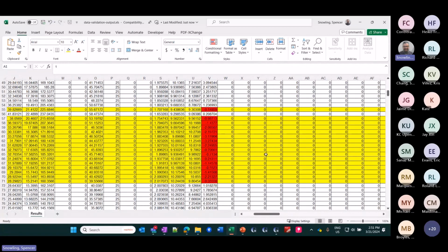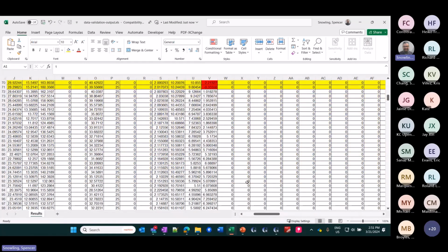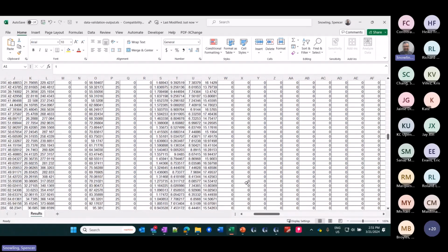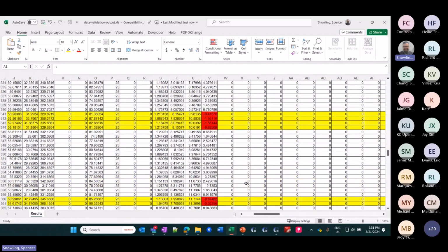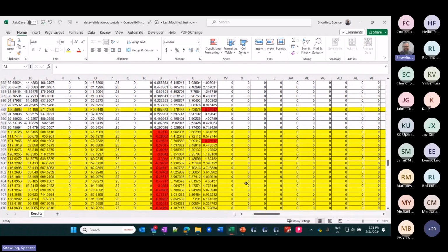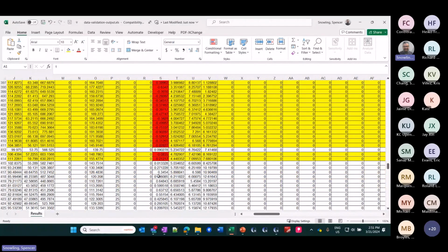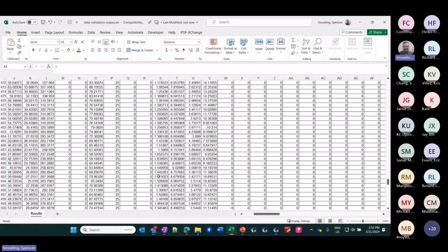So it immediately says all of these rows are a problem because one of the states came out negative. And in fact, if I go down farther, there are a number of other ones here too. We can see there are some more phosphorus ones. This is actually SND, a soluble organic nitrogen. So that's another time when some calculations for nitrogen came up negative, and so on and so on.